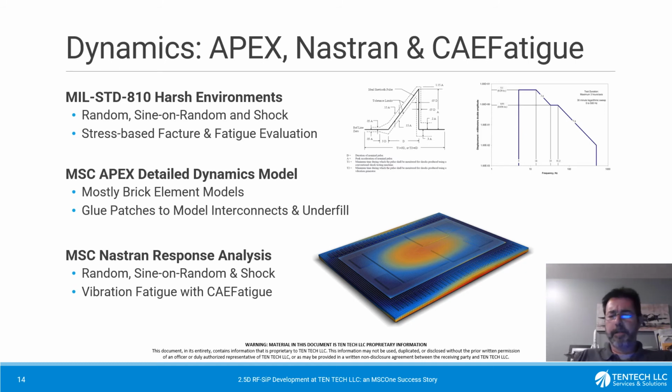And again, those military environments, MIL-STD-810, are designed to represent a service life of 5 to 10 years in a military environment. So they're extremely harsh in terms of level and duration, and it's critical that we calculate this very well, as you can't have a failure in the field.